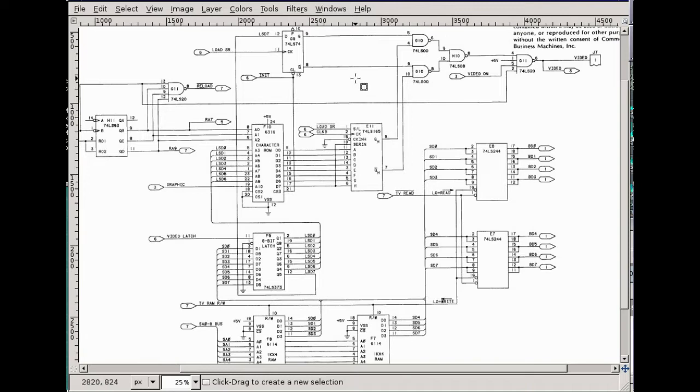What we understand from the random character screen we see with no CPU, or when the CPU has not yet started, is that most of the video output circuit is working, particularly the dot clock and dot shifter integrated circuit, because the characters are still well formed and stable, no flickering at all.